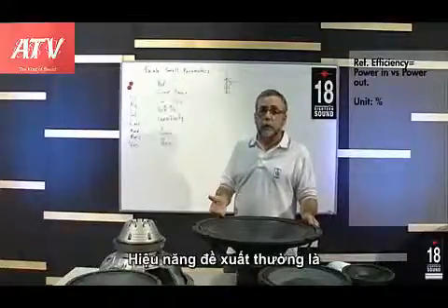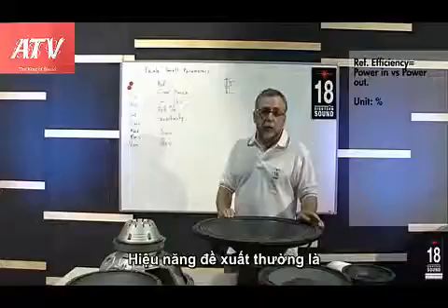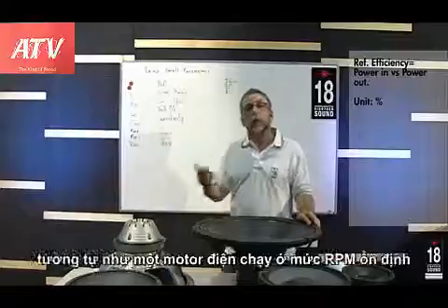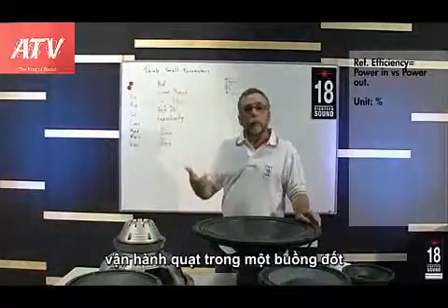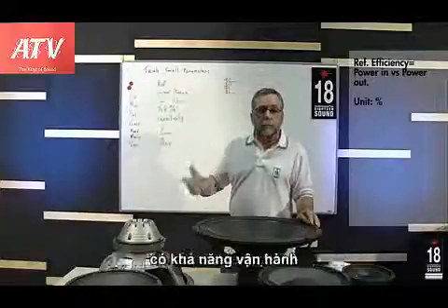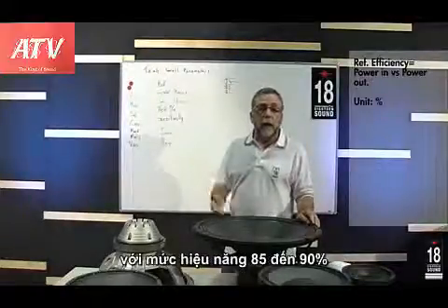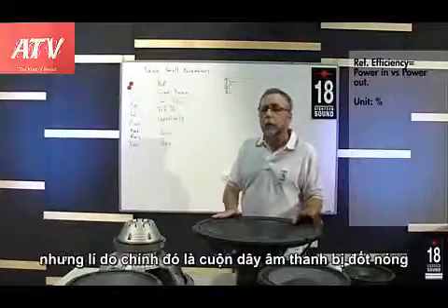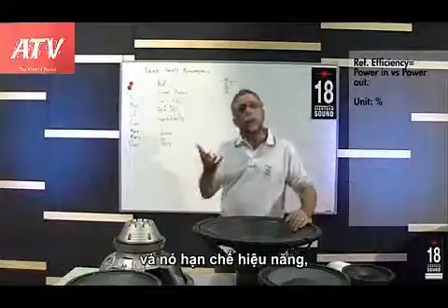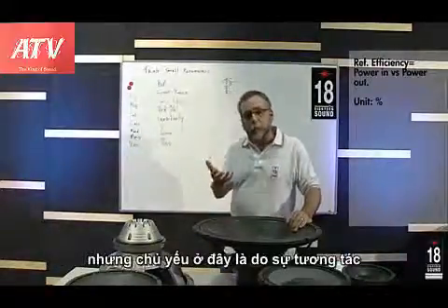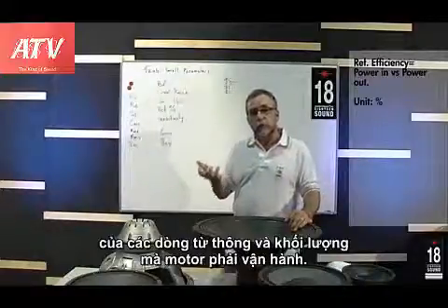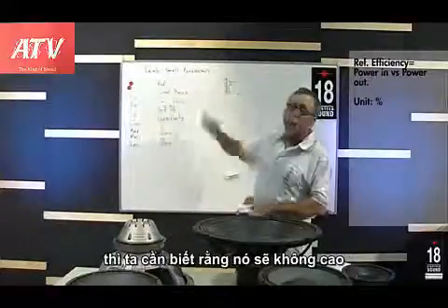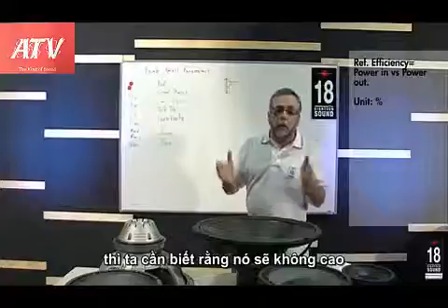to 50% efficiency. The woofer efficiencies are very, very low relative to many other kinds of mechanical devices, like an electrical motor that would run at a steady RPM and say run the fan in a furnace, which can run at 85, 90% efficiency. Loudspeaker motors are very, very poor. There are a couple of reasons for this, but one of the primary ones is that the voice coil gets hot and it reduces the efficiency. But mostly it is about the interactions of the flux and the mass that the motor has to move, thinking about a very large gap of magnetic flux that is not as high as we would like it to be.